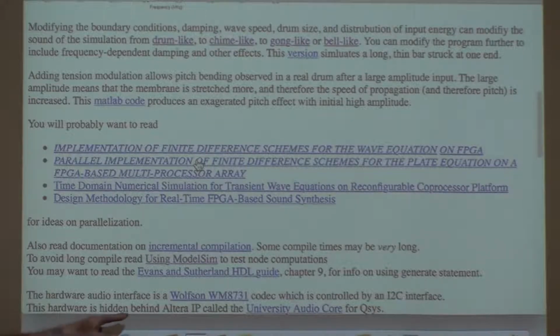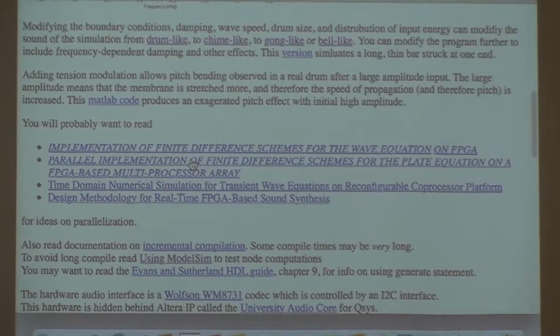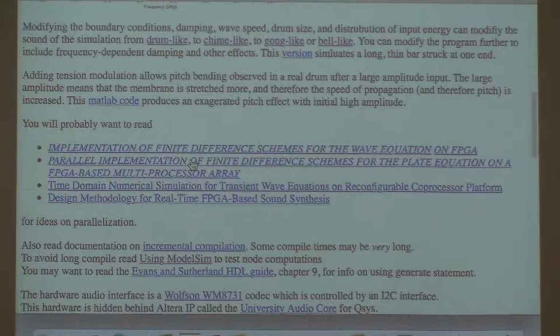But this is a completely separate piece of hardware on the board with its own state machine, which occasionally gets hung up. And it turns out that if it gets hung, you can't unhang it except by cycling the power. And on our boards, you must bring down Linux before you cycle the power. So you'll have to unboot, recycle, and come back up again. So hopefully that won't happen. I haven't seen it happen yet on these boards. The old boards had it happen about 1 time in 10.